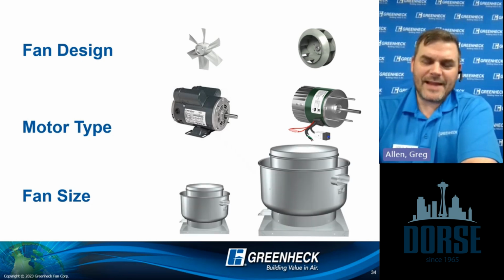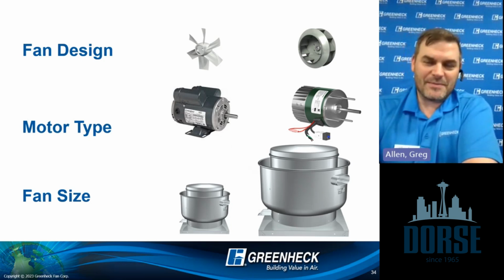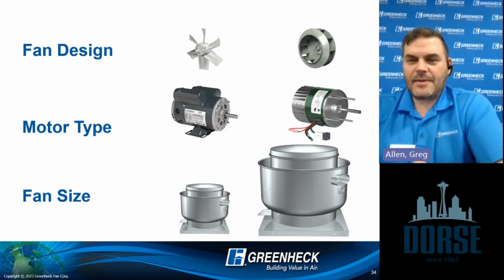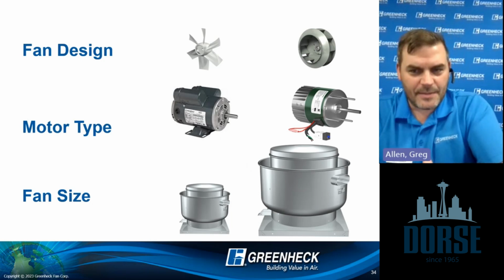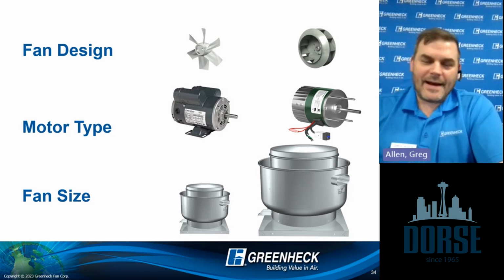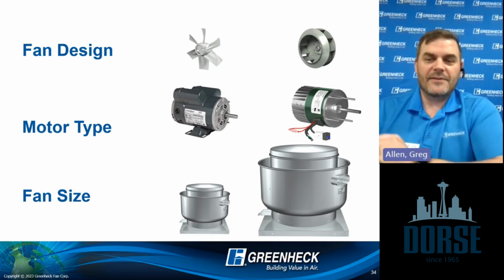And then that last point I made on the previous screen: fan size is the next thing. Today I might use that smaller fan shown on the screen. Tomorrow, to hit the higher FEIs that are required, one of the things I should be looking at is, can I up the motor technology? Can I go from AC to EC? How much efficiency does that pick me up in that design? But you may also want to look at, okay, I need to bump this up to an 18 or a 20-inch wheel in order to get me to where I need to go efficiency-wise.